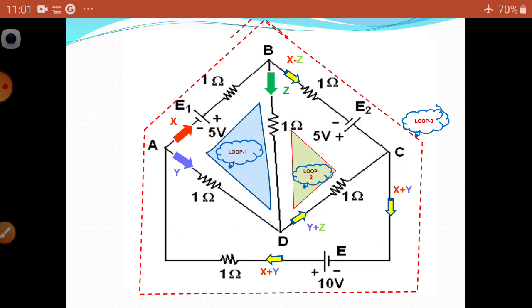Based on this, let us do this. This is the procedure. First, assume the circuit and consider the loops. At the same time, based on the voltage sources, assume the plus and minus of each element, and after that apply KCL and KVL. Then you simplify the equations and you are going to get the unknown values. The same problem we can do in a good manner.